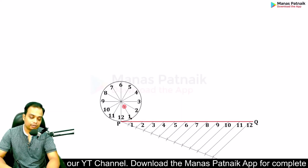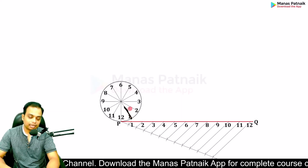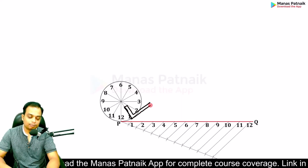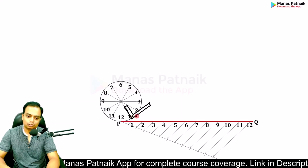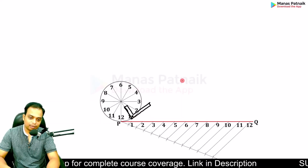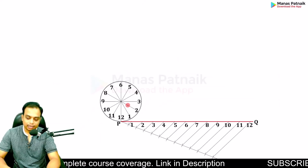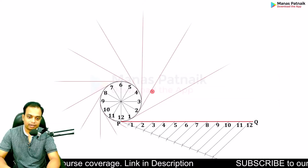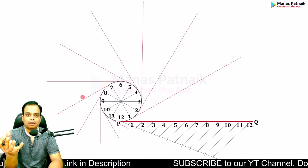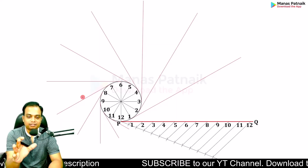What we basically need to do is keep one scale of your drafter over here, while the other scale will automatically be perpendicular, right? Tighten the screw also. So through 1, with the help of this scale, draw a line. This automatically will become a tangent. This way, in case of 2 also, make a tangent. And through all of these points, in fact, you need to draw tangents. I expect you guys to make tangents easily.